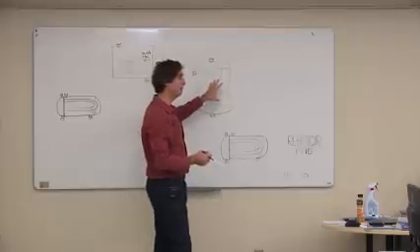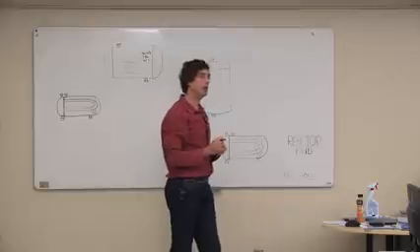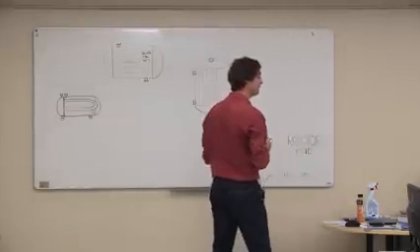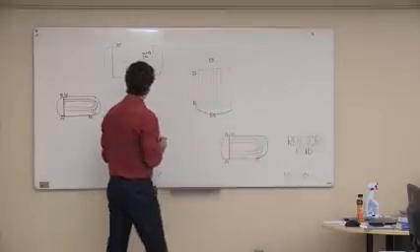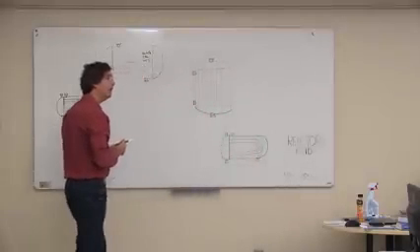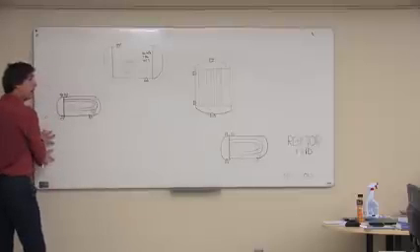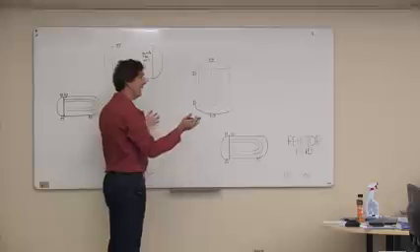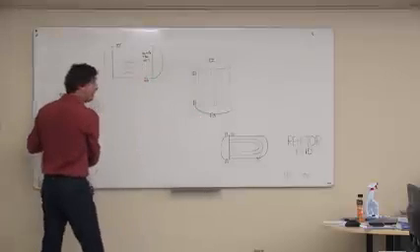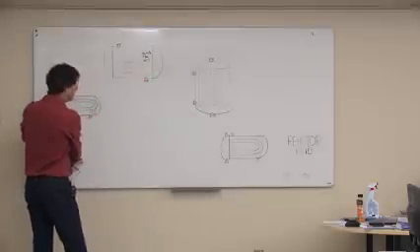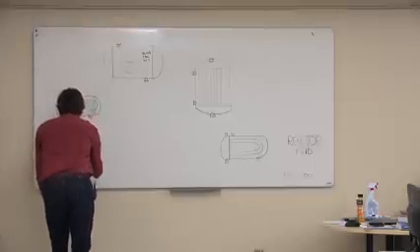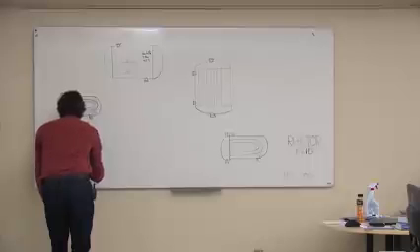Anybody got HYSYS open? Check the exchanger operating pressure maybe. I'm not sure whether it's built into that model or not. I would say though that if we've got 6 bar coming in the sheet and we're trying to operate the steam system at 10 or something like that bar, we need some feed pumps in here. So my recommendation then is to put some pumps in here.